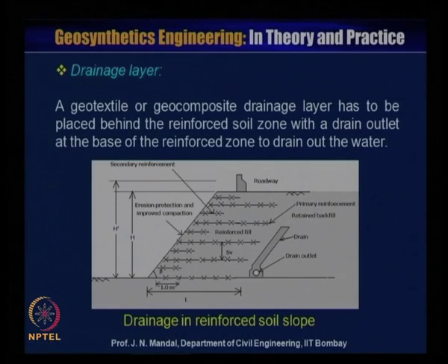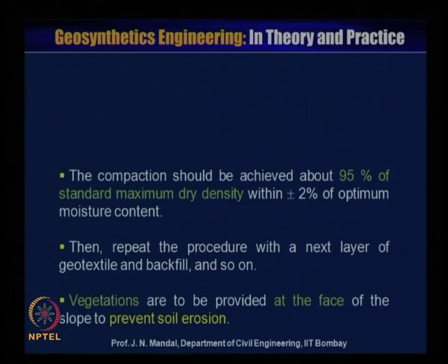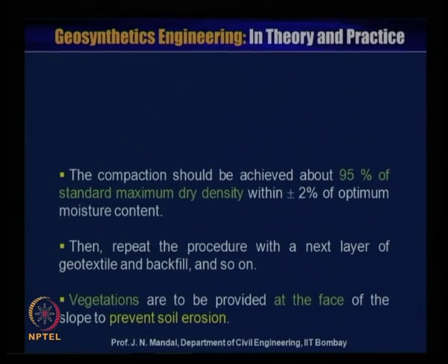So, you can have some idea of how you can place this geotextile material and how you can construct the slope using the flexible material, how you could wrap, how you should compact, and what density you should achieve, in order that there should not be any sloughing of the slope or any erosion at the face of the slope.